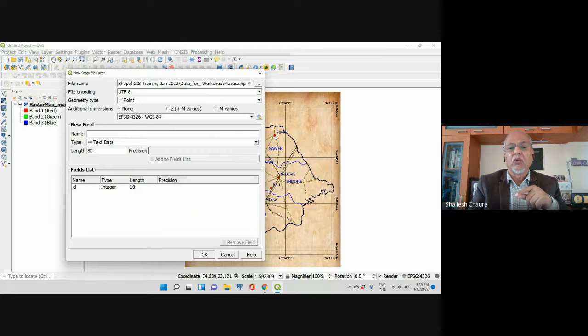So I would like to write the name there, but I may be interested in writing the population of somewhere, the name of the district administrative officer, the male-female ratio, the eligible voters, number of tube wells, number of schools, so many things. So I cannot write everything on the drawing itself. So that information I will write somewhere in a table. So that table will be created here itself. So add fields. Right now there is no field added to my data.